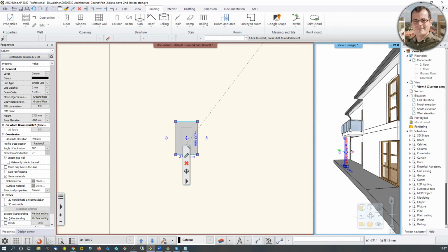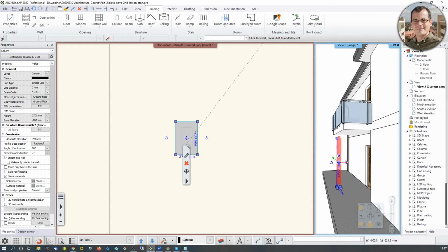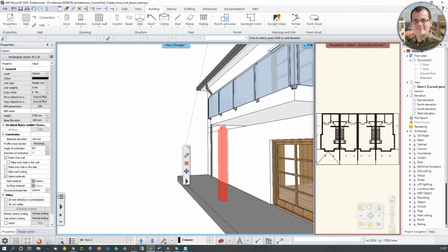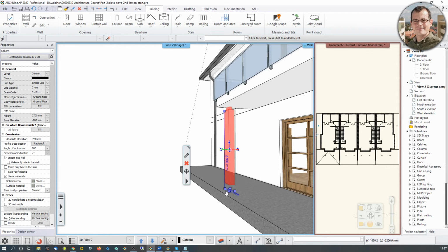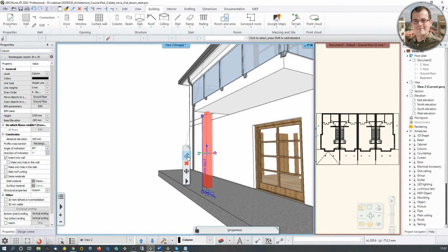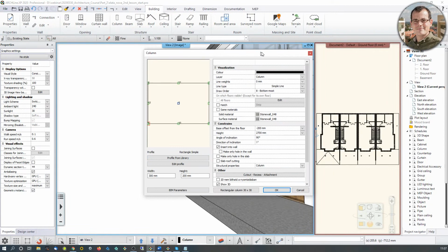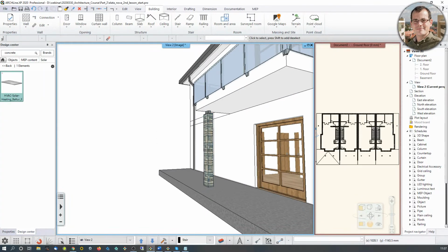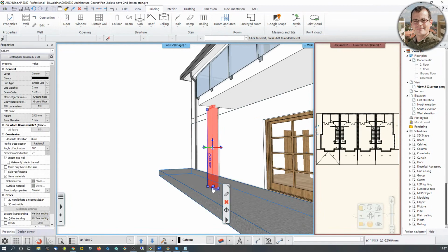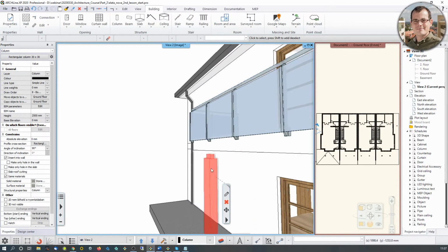Are we done? No. And the reason why we are not done is because this column is not reaching its height. Why is that? What happens if I realize that this column is being pushed into the ground? So if I compensate for the base elevation, then this column should reach its height, right? Well, not really. And that's rightfully so. Let me demonstrate. If I go to the settings and I crank up the base offset to 0, I see that the offset is now changed, but the column still doesn't reach its goal.